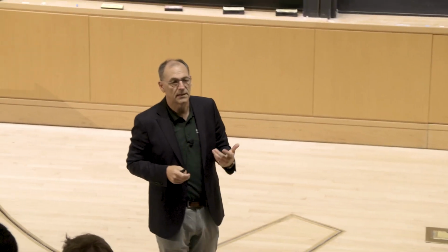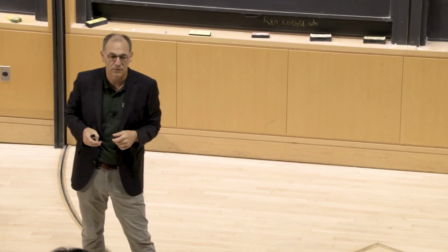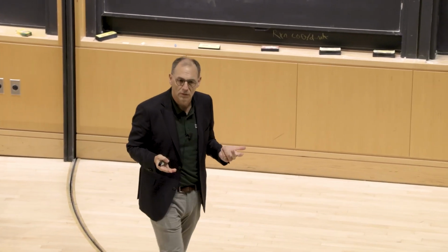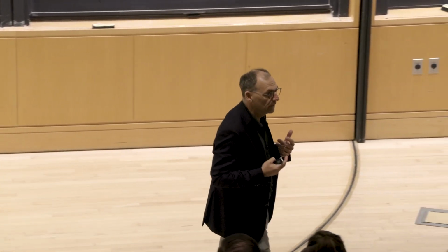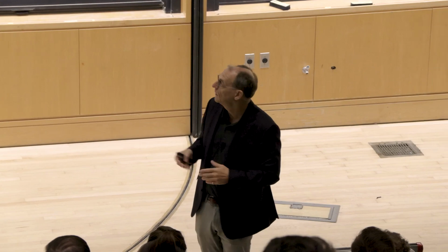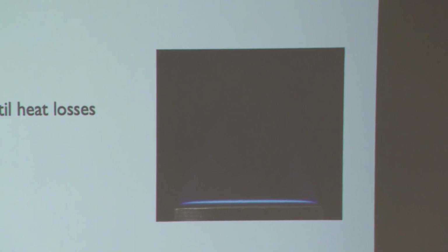So you might see experiments in premixed flames under subatmospheric pressure, and you think, why in the world? We're interested in gas turbines. That's high pressure, or we're interested in whatever. Many combustion applications are high pressure. No combustion application is low pressure, okay? But they do this because it's easier to measure. But still it's difficult. You always have the burner and the flame, and they interact very strongly.